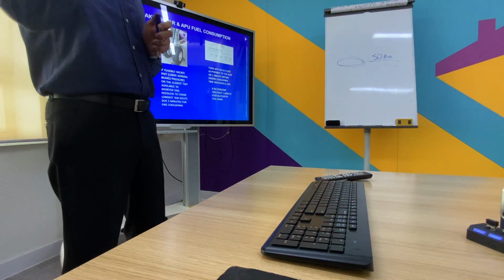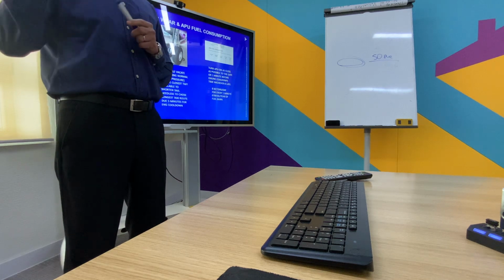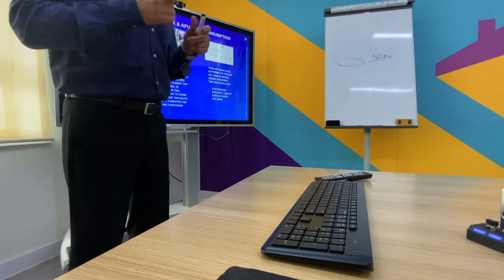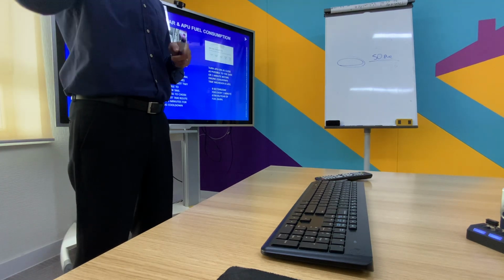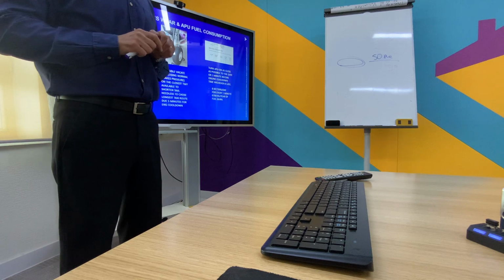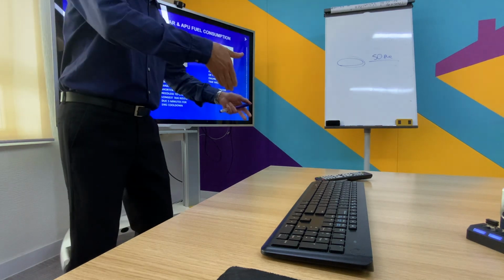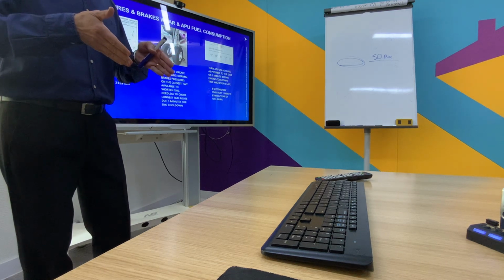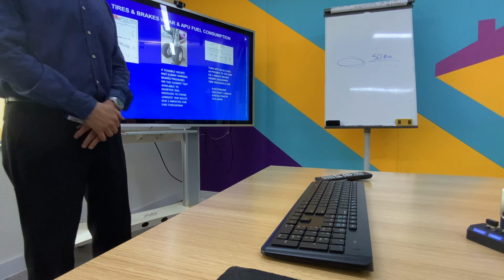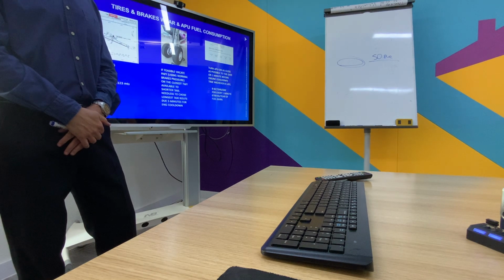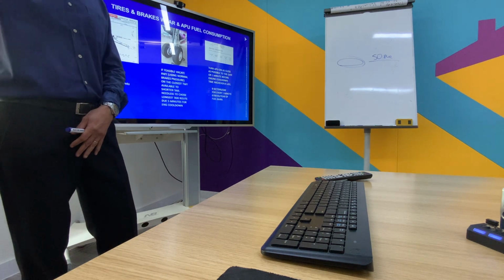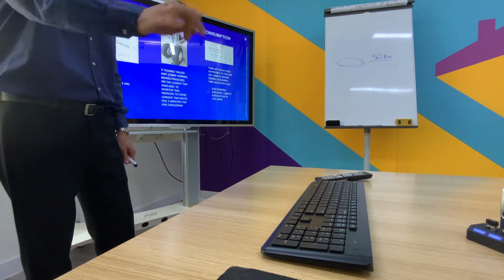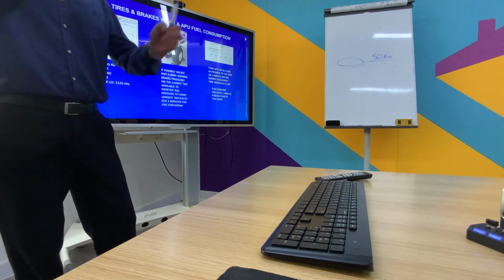Before entering the gate, what I do, before asking for taxi light off, I ask for turn on the APU. When you stop the airplane, the APU is on the line and you can shut down the engine and save fuel from the APU. If you are on the E2, as we have the 5 minutes cool down, if I park the airplane at the gate and I have to wait 3 minutes, APU off. No need to turn on the APU. 1 minute before, shut down the engine, APU on, with the airplane parked, APU on the line, 5 minutes, shut down the engine. You are saving fuel.